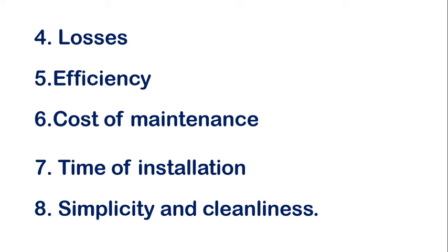Next one, that is the time of installation. So time for installation is the highest in case of hydropower station, as a large civil engineering work like dam, canal, tunnels, penstock, etc. is involved. The time for installation for the nuclear, thermal and diesel power station is in decreasing order. And the last one that we are going to talk about, that is the simplicity and cleanliness.